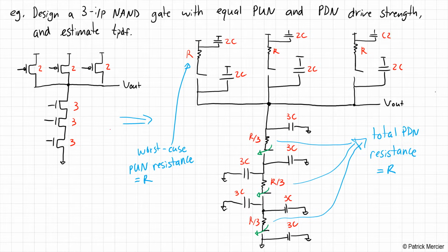All right. Now, there's a few other simplifications we can make. We can, of course, get rid of that capacitor. These PMOS capacitors, because they're connected to VDD on either side, they don't participate in charging or discharging in this particular circuit. All right, so this is still a little bit complicated. So what I'm going to do is combine all of the effective parallel capacitors that I can and make a slightly more simplified circuit for us to analyze. All right, so that's simplified.